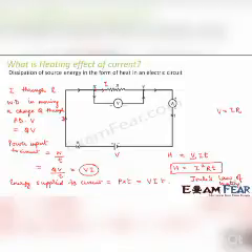So according to Joule's law of heating, if you have a circuit where there is a source which provides some amount of source energy because of which a current I flows through the circuit, then the heat that is dissipated across the resistor is given by I square RT, where R is the value of that resistance and I is the current flowing through the circuit, right? So this heat is useful for many different applications. We will look at some of those applications in the next few slides.